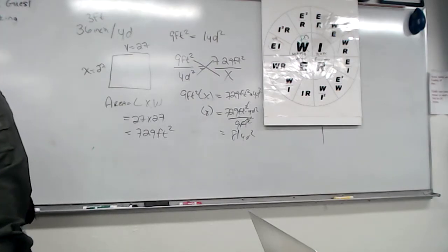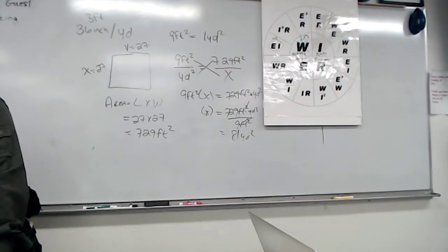So we're looking at something that's 1.5 inches. And it's not going to be a round octagon box. Is that fair? It's not going to be a square box. Is that fair? It's probably going to be a device box because it doesn't look like a masonry box.